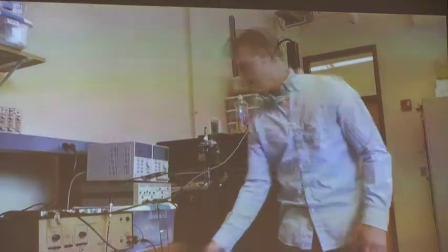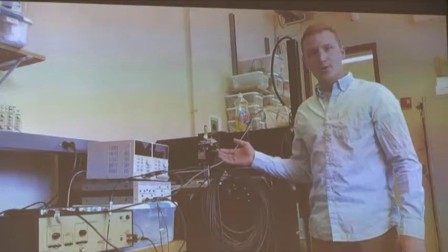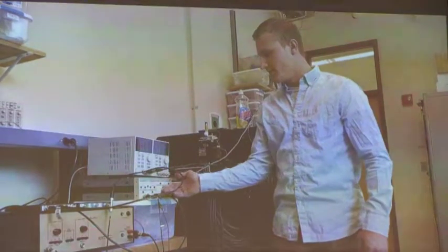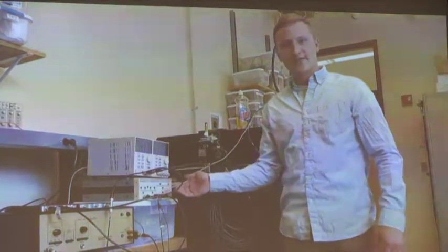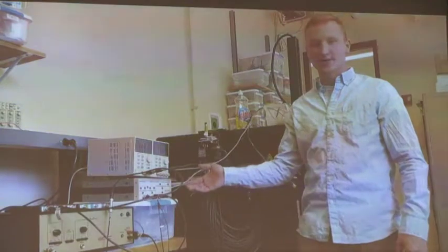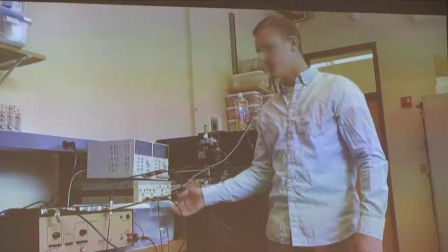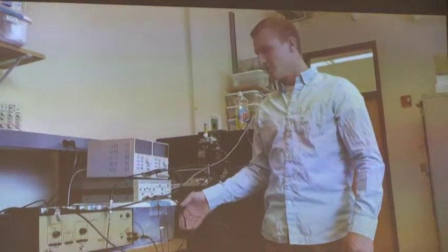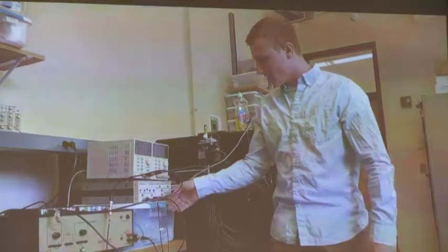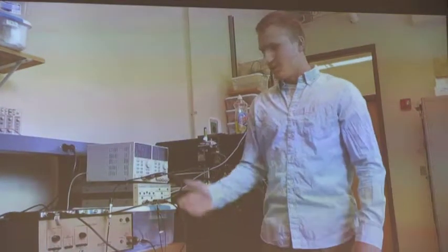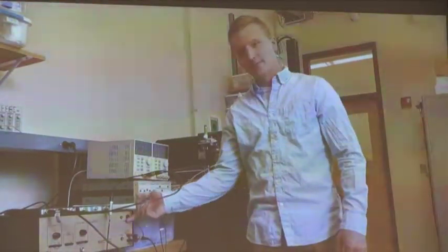transmitting transducer. Due to the attenuation through the wire, we're going to need a preamplifier. For the preamplifier, we're going to have 50 times gain. The preamplifier will clear the signal across the pin. We'll have the output connected to channel 2, on which we'll be able to see the receiving end of the signal. Now that we've got all the hardware set up, let's get started.